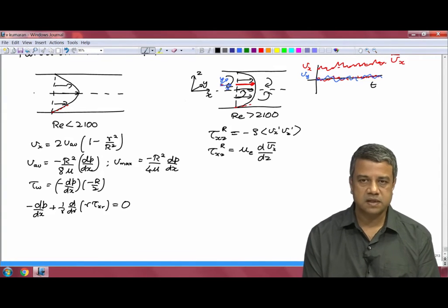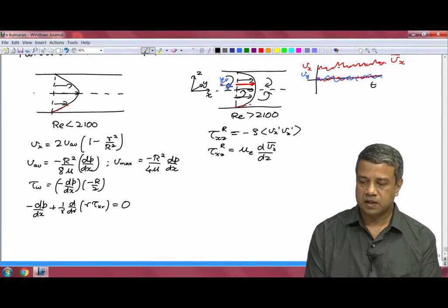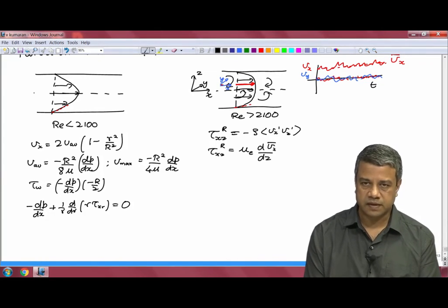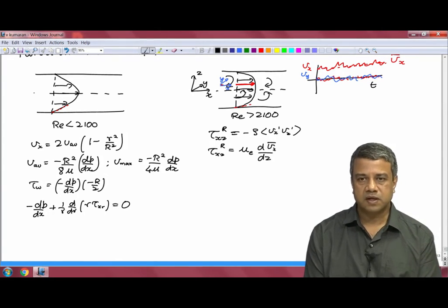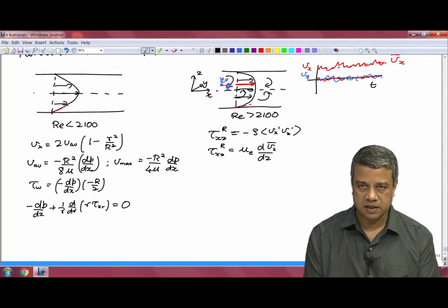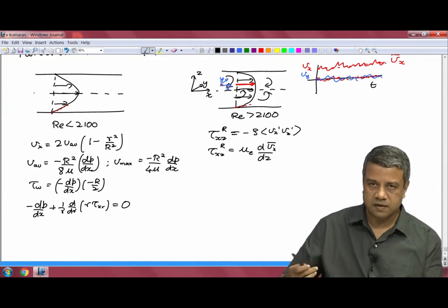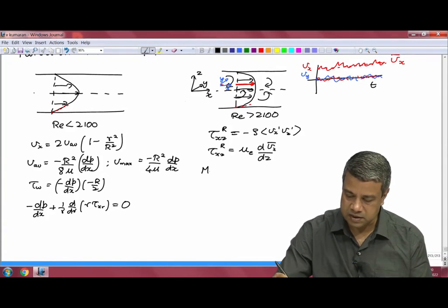The eddy viscosity is a flow property, because it is the flow that is convecting momentum across the flow, these parcels of fluid that are convecting momentum. So, because it is a convective effect, it does not depend upon the molecular viscosity, it depends only upon the particular flow, that is the flow Reynolds number will basically determine what is the eddy viscosity. And the models for the eddy viscosity are what are called the mixing length.